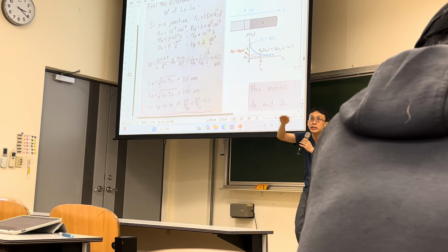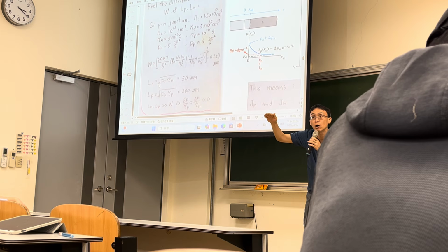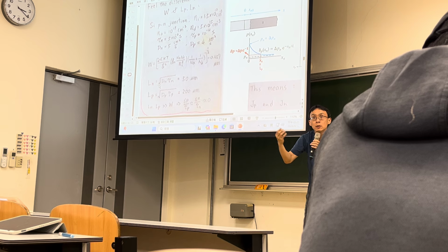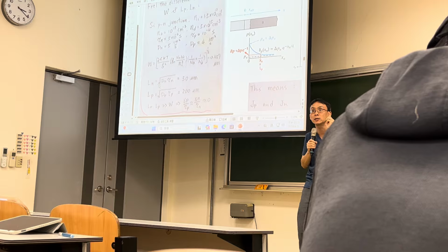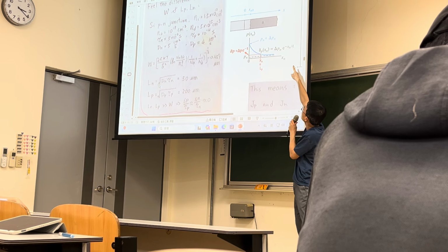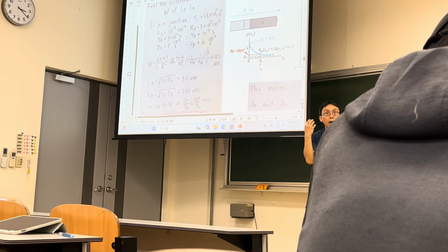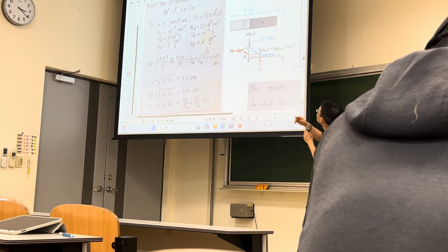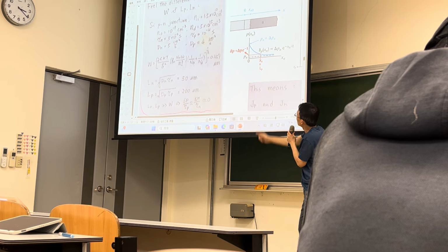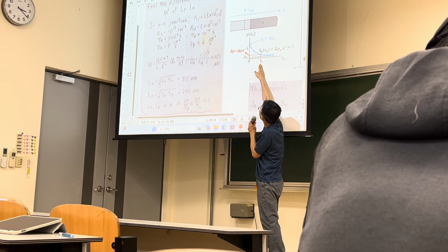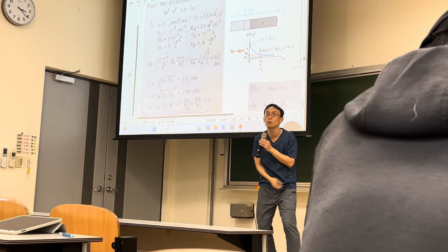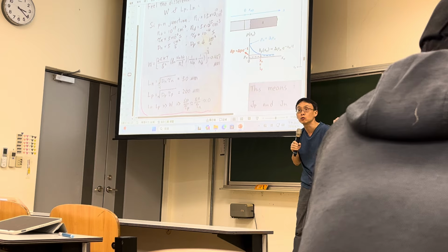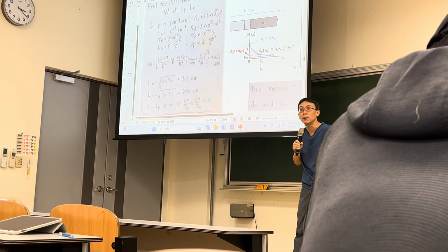L is in the denominator of the exponential term, right? So if your diffusion distance is the same as the diffusion length, which means xn in the exponential term is equal to L, what happens? Your hole concentration decreases down to this red dashed line point, e to the power of -1, which is 1 over 2.71828, right? What does that mean?